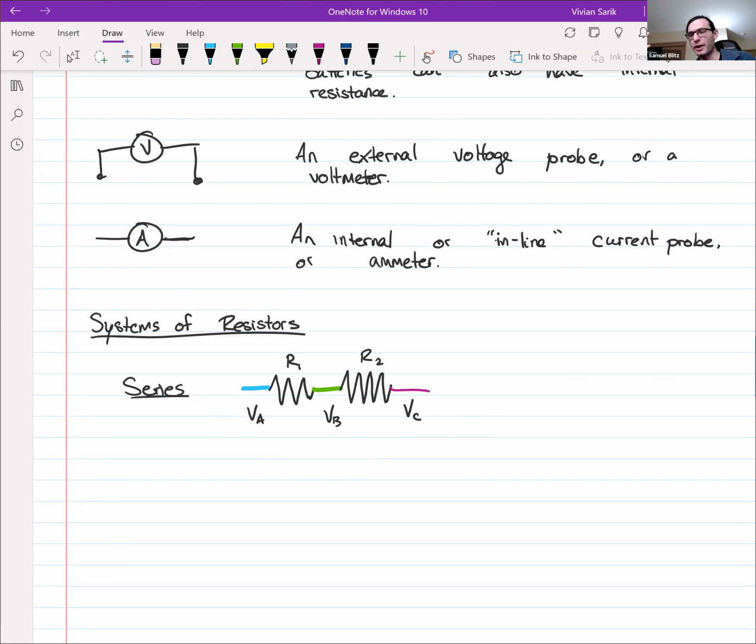Just like when we were talking about capacitors, we had to establish a constraint. When it was capacitors, we said that if the two capacitors are in series and the conductors are neutrally charged, then the charges on the two innermost plates have to be the same, because one will be positively charged, one negatively charged. And because capacitors always have equal and opposite charges on either plate, the magnitude of the charge on each plate is the same on all four plates. So we need a similar type of argument for the resistors.